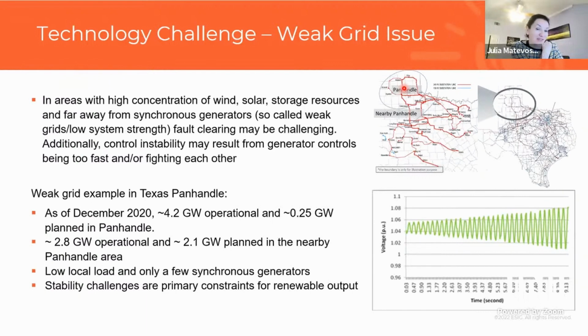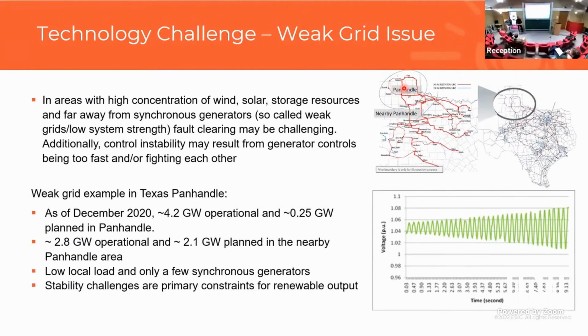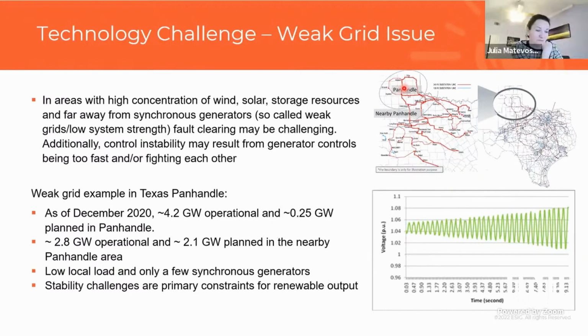So it's just a practical issue. Just for simulations, it makes sense to install certain hardware on the system rather than going for more advanced inverter controls. Because even with grid forming inverter controls, there still will be a need to do detailed EMT studies. Okay. Thank you, Julia. So it's a tail wagging the dog, essentially, just simpler simulation. Yes. It means that they don't use more advanced controls.